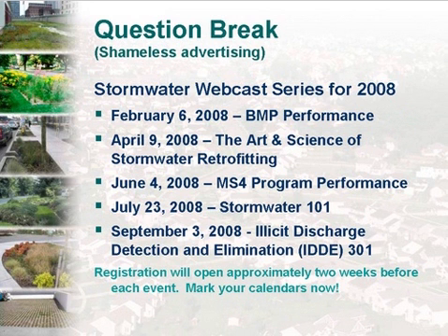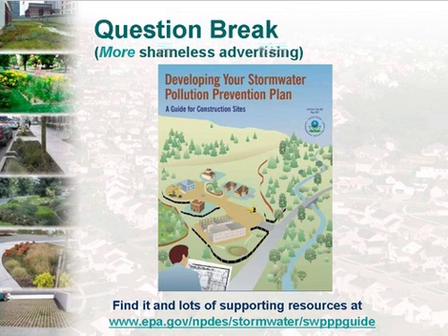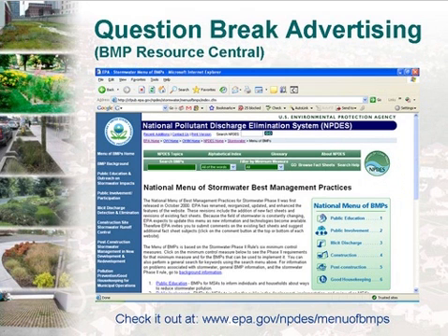Well, Lawson, excellent question that you posed. Certainly all of us are very interested in how well BMPs perform over time. I'll share one specific example with you. We have been monitoring, at a residential development in the western Denver suburbs called Grant Ranch, the performance of a stormwater treatment system for 8 years. We're actually moving into our 9th year. And we're pleased to report that we've seen no deterioration in performance over time. This facility basically consists of homeowner covenants on the non-structural BMP side, followed by 3 extended dry ponds, all of which feed into a water quality wetland pond. The performance has been excellent. It's not deteriorated over time. And if you look at our database and the Center for Watershed Protection database, you can certainly find, Lawson, multiple studies that have multi-years of data that get at your question.